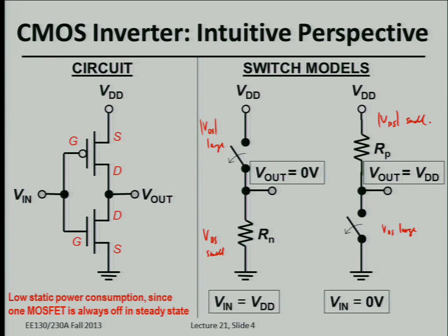Okay, so one key thing to note is that if there's any leakage current, even though a transistor is off, in reality, there's always going to be some non-zero leakage current. So there's actually going to be some I off, off-state current, flowing through here. I off for the PMOS, I off for the NMOS in the opposite case, okay? So basically, even if your CMOS circuit is not doing anything useful, it's just holding this steady state, it can consume some non-zero power.